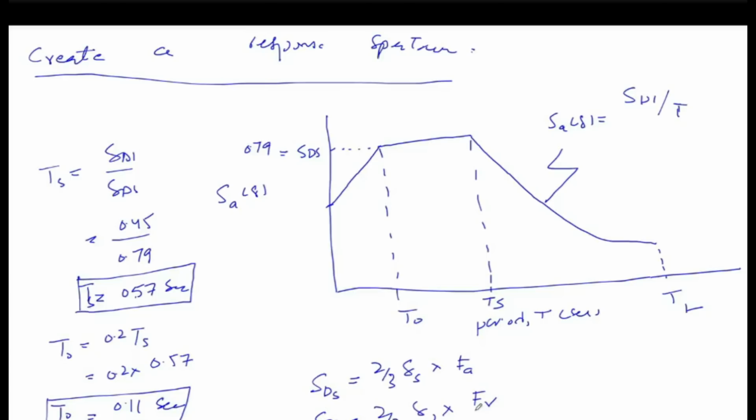Okay, so once we obtain the response spectrum, how do we use this further? The next step for us is to calculate modal forces and story shear.